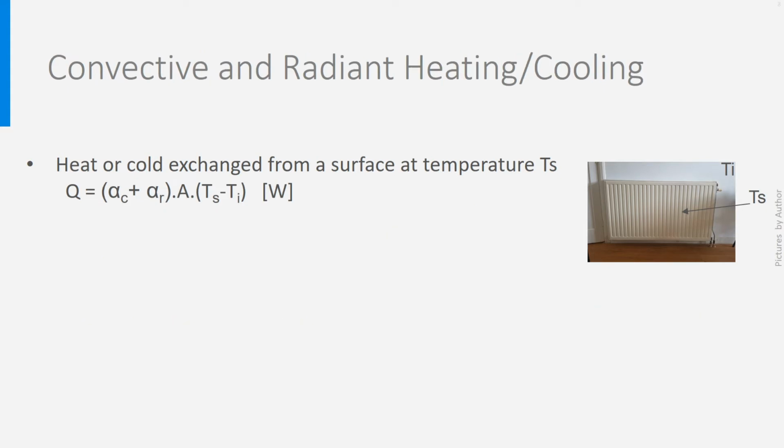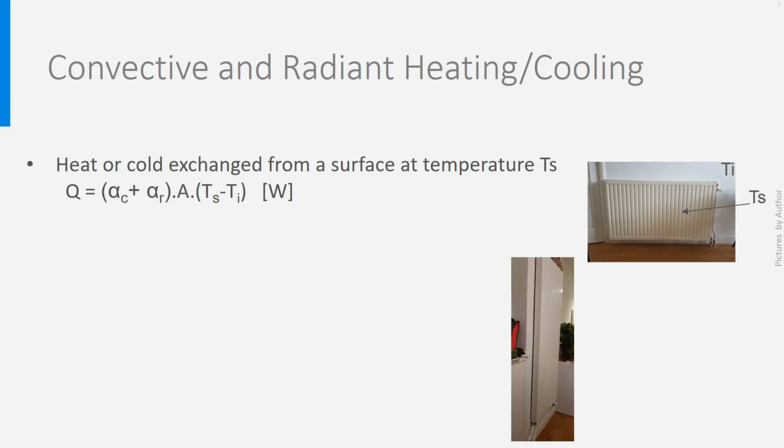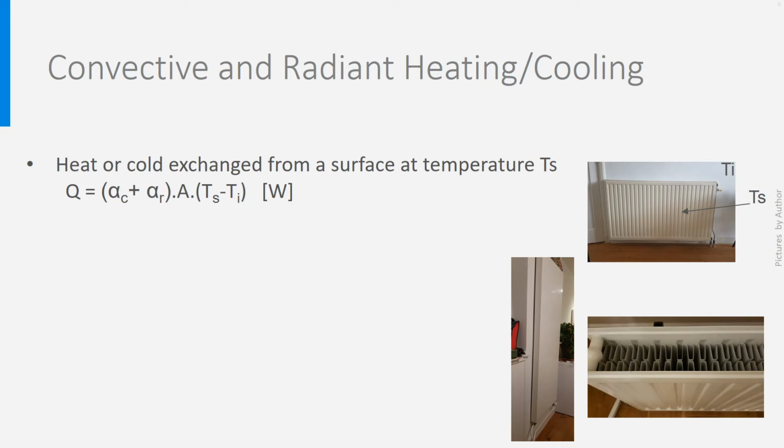So, in the heat exchange, there is always a convective and a radiative part. When it comes to products on the market, it is very confusing what is called radiant heating and what is called convective heating. In fact, all products always have both, according to the laws of physics. However, in some cases, the device has just one flat plate, like this one. In other cases, the plate is corrugated, like on the radiator above and this picture. Additional plates are added, increasing this way the effective heat transfer surface for convection.